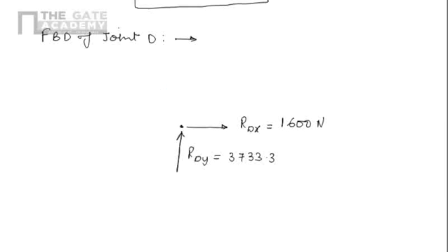And there are two members. So according to our assumption, the forces in the members are tensile. So the arrow will be away from the joint. And the force is FDE, away from the joint. So this force is FDC. So we have to apply the condition based on y direction. So the equilibrium condition based on y direction is nothing but the algebraic summation of all vertical forces should be 0, or forces along y direction should be 0.